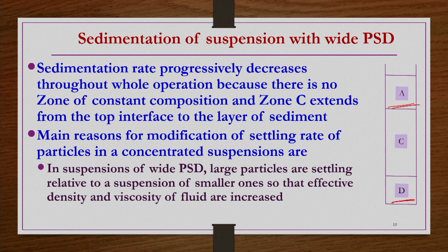Let us say you have a slurry in which the particle size distribution is very wide, a few microns to a few mm, let us say 1 micron to 2 mm. The micron size particles are mixed in the feed slurry. These very fine particles have a very small settling velocity. So, when they are mixed with the liquid, they form a new suspension whose effective density may be much higher than the initial liquid you have taken.